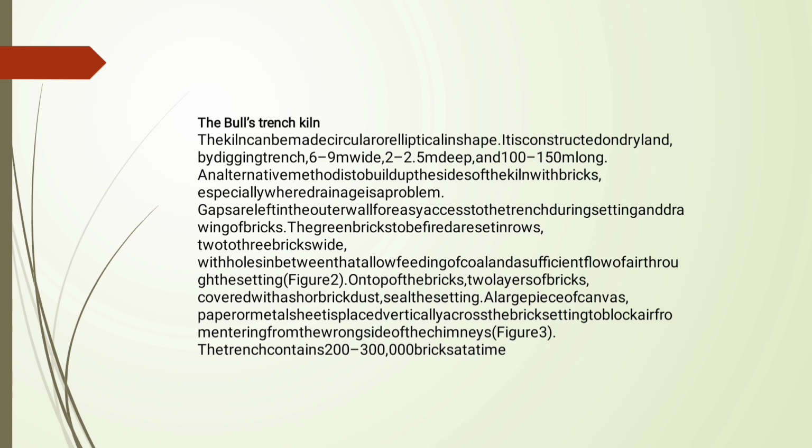The bricks are arranged in sections and flues are formed. The fuel is placed in flues and it is ignited through flue holes. The top of each section being ignited is covered from top with earth and ashes to prevent escape of heat. The flue holes are provided in sufficient number on top to insert fuel when burning is in progress.